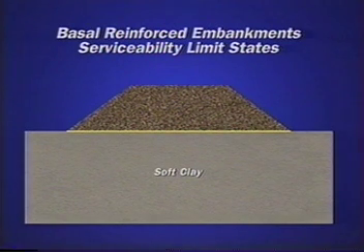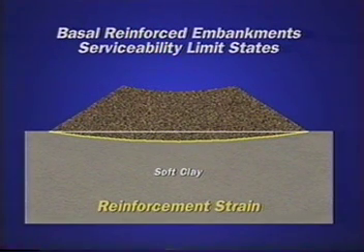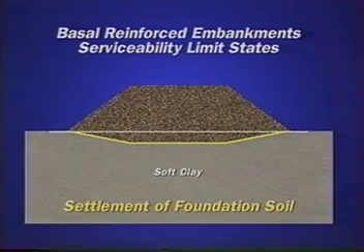It then remains to assess failure mechanisms leading to serviceability limit states. These include limitations placed on tensile strains developed in the basal reinforcement and settlement of the foundation soil.